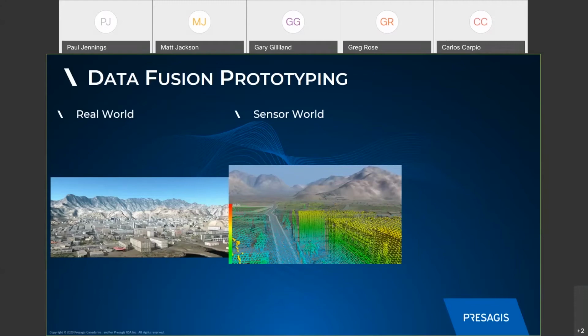What you're looking for is the sort of thing that you want to present to the actual end user in the HMI. So this processing could traditionally be done with a separate computing board or something like that to give you that information. But with the advent of multi-core or multi-partition systems, we can actually use a single board and use the power of GPU processing to do compute to actually build up something that's useful to present back to the HMI. So in this particular case, we've used compute to say, actually, here is your flight plan within this area in a 2D representation, top-down view.